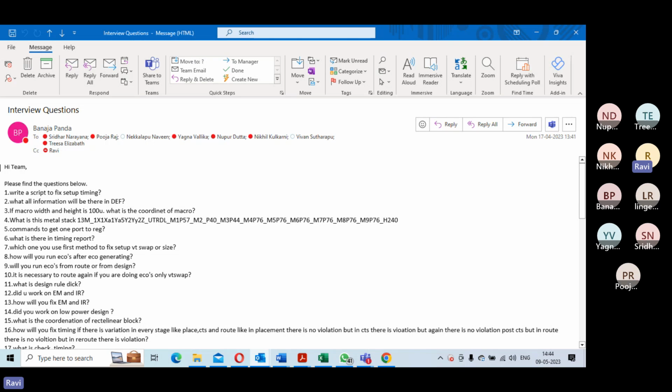But if it is like 4 input or 3 input, it could be like that. Complex cells may come to 50 picosecond, something like that. So if any delay is more than 40 picosecond, you collect those things. And if you see that their drivers are small, you just do an upsize. So that means sort out, okay, uniquify. This is what your script should do.